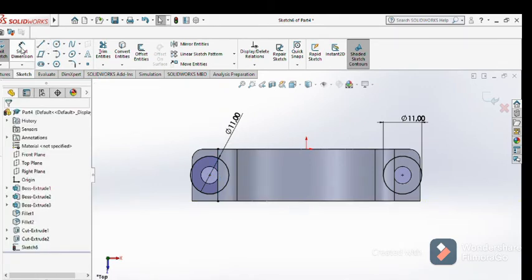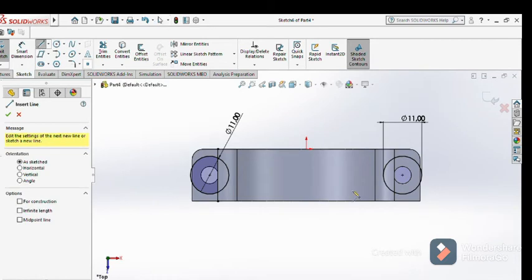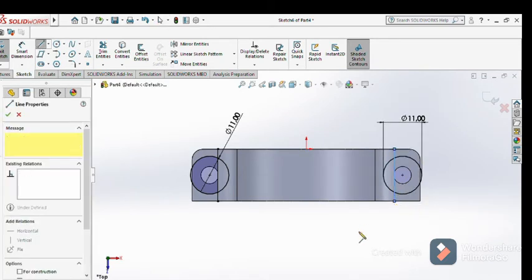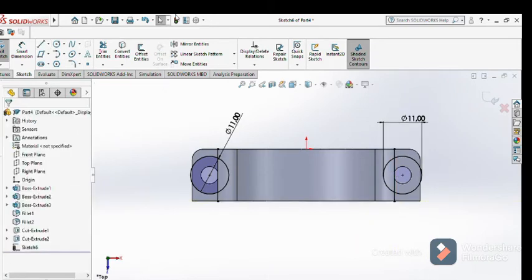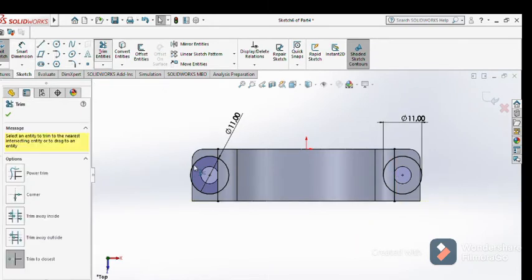And then I need another one that cuts through there. The other parts you don't really need. You go to trim entity, you remove, and you remove. Once you're done with that, let's remove this side and this side as well.